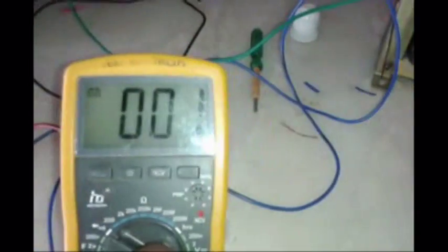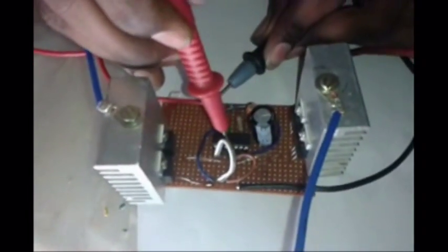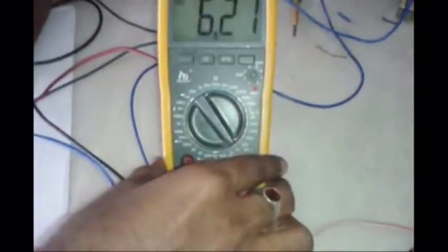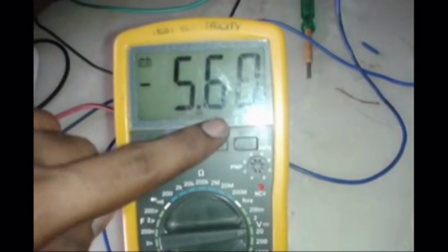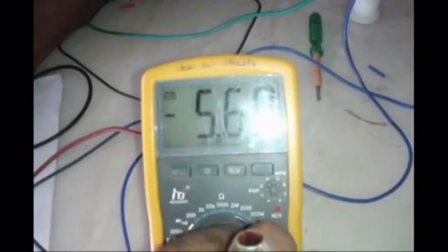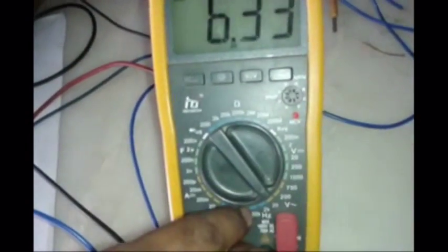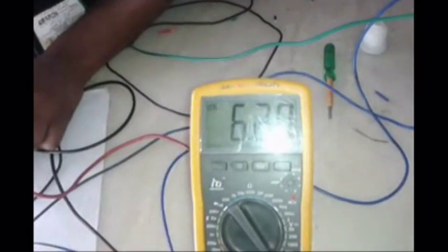So give the input. Now if you see in the multimeter, I'm putting a 20 volt range. Now we are checking the output across the 10th pin and 11th pin. You can see 6.23 volts. It's an AC voltage, and the rest of the component you can see as a DC voltage. Now I'm turning it into a DC voltage. So you can see the rest, 5.67. So it's a DC component and that was an AC component. Since a square wave is a combination of DC plus AC, this is what is happening. 6 plus 5, it's almost 11 and 12.